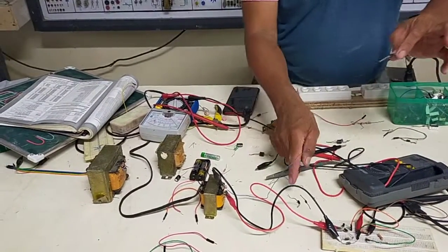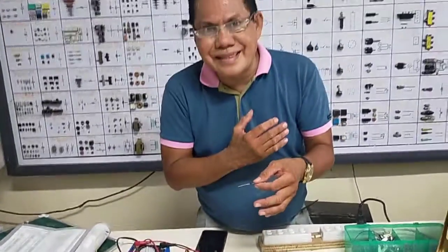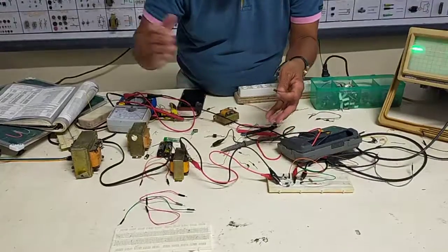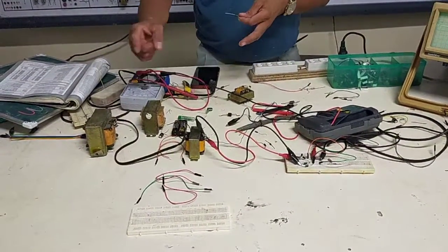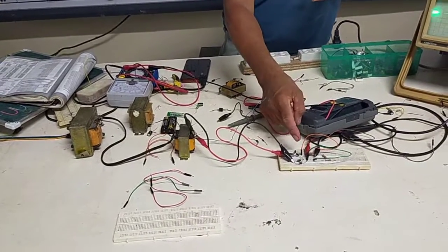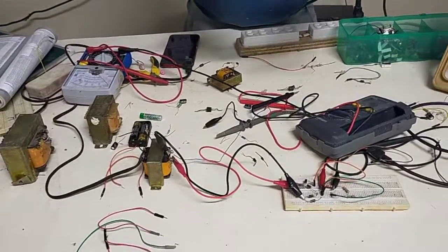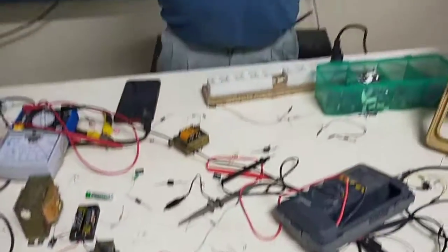Because if you are using 2 amperes or 1 ampere, the diode during operation will become very hot, because the current rate of the diode is not enough to control the intensity of the current outputted by the transformer. If the transformer is 6 amperes and you are using 2 amperes, these diodes will become hot until they destroy the diode. Okay, that falls under the current rate.